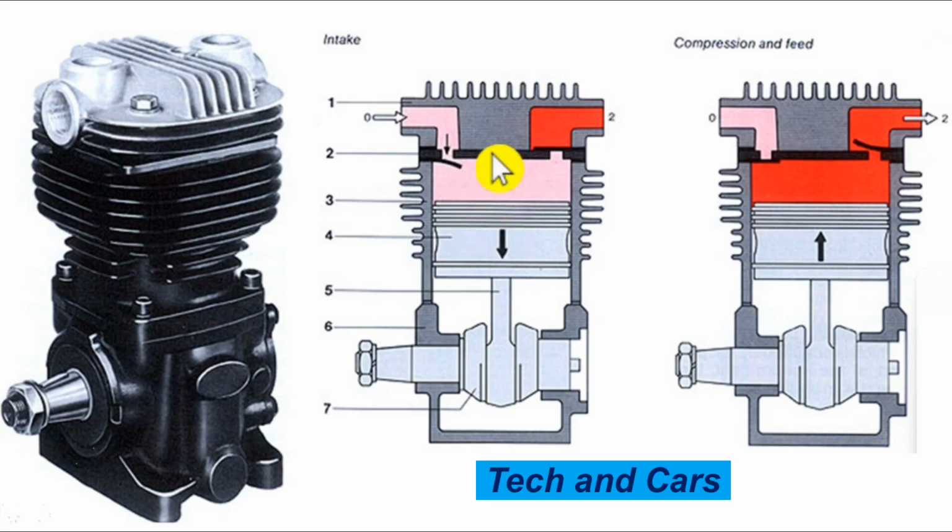And the other thing that can cause low pressure buildup is if there is a clogged air filter. Air that is being fed to the compressor has to flow readily. If the compressor is being choked, if it is unable to get enough air to compress, that can also cause the air compressor to build up pressure very slowly.